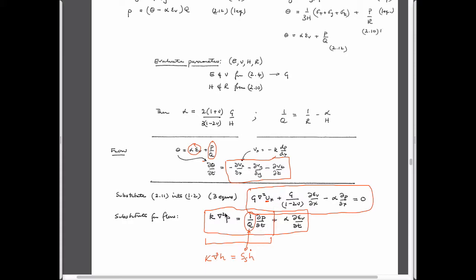And so as a result of that, certainly when we solve flow equations without this strain term, we can do that without having any other information other than just fluid pressures. And usually the assumption in groundwater hydrology is that total stresses don't change. And so if you have a packet of stuff and you change the fluid pressure in that packet, then the only thing that happens is you get compression of that packet due to the same total stress that acts down. You're not modifying those stresses as you go through it. Poroelasticity allows you to be able to do that.